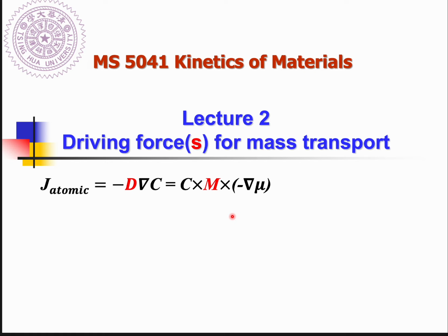Let's start lecture 2, talking about the driving forces for mass transport. For mass transport, the first thing that probably comes to mind is atomic flux, which can be used to quantitatively describe the mass transport. As you learned from Fick's first law, atomic flux equals minus diffusivity times the concentration gradient. You also know that the atomic flux equals the concentration of diffusing atoms times the mobility of diffusing atoms and the driving force.